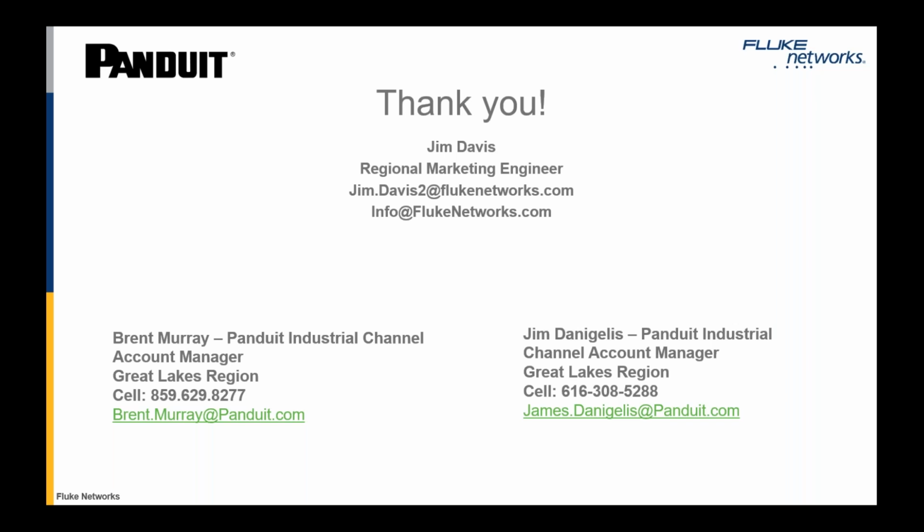I have not seen cases where Category 5E cable is going to pass Category 6A performance, especially when we get into longer lengths. So I think that would be very difficult to see. If you have a shorter Category 6 link, could that support 10 gigabits? Yeah, it might support 10 gigabits. There's an expectation that it'll run out to about 50 meters, but running 10 gigabits on Category 5E cable would be a challenge.